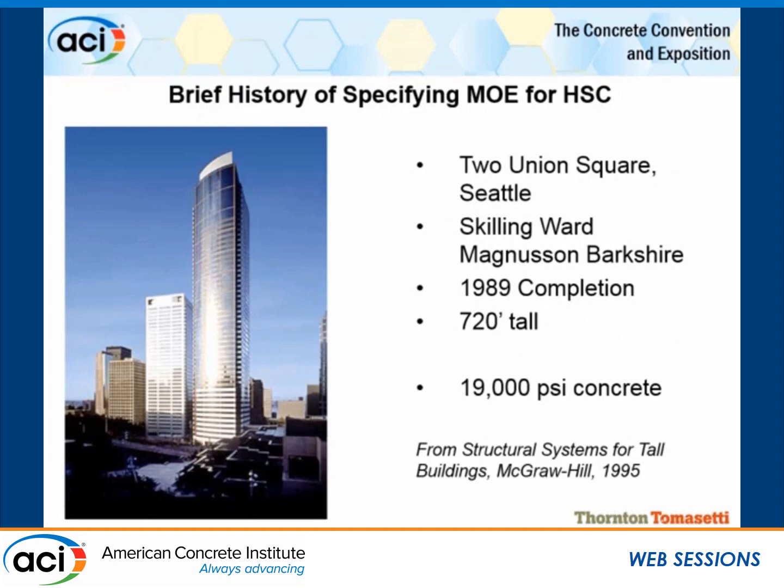Just a little bit of history, because I think it's important to understand where we were and where we came. One of the first projects in the literature that started to address the issue of MOE for tall buildings was 2 Union Square. It was finished in 1989. Not that tall, it's just 720 feet, still a very significant project. They specified 19,000 psi concrete, and at least from the literature, the idea was that by doing that, they would sort of back into a target modulus of elasticity that they needed for the stiffness of the tower. So that was one of the first attempts at getting at this issue of what's the modulus of elasticity for that particular project.